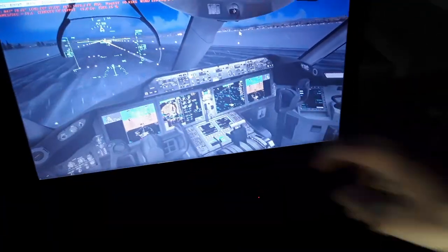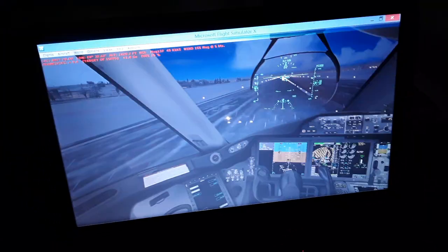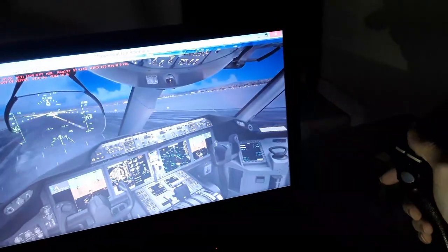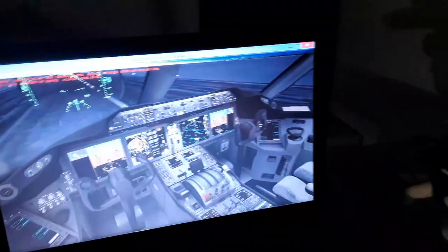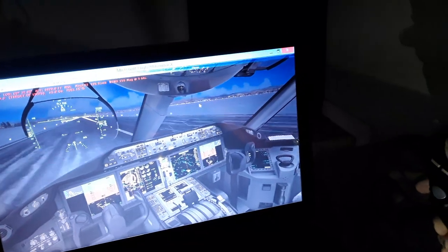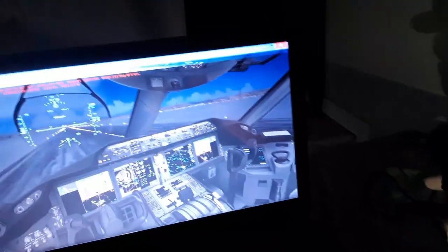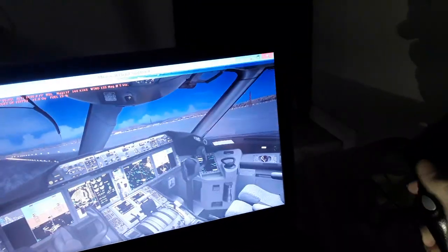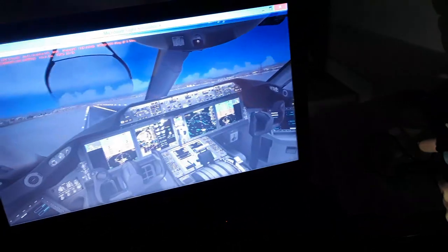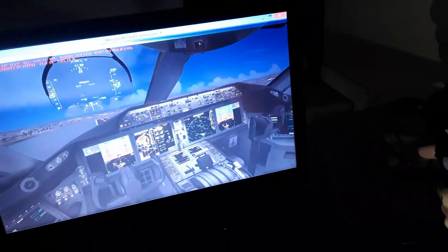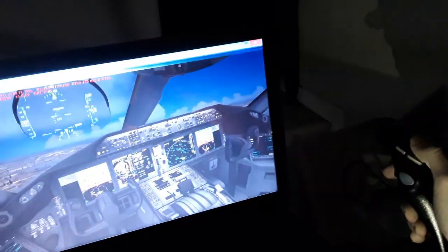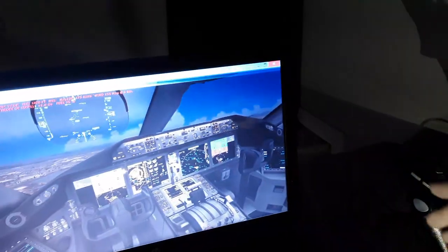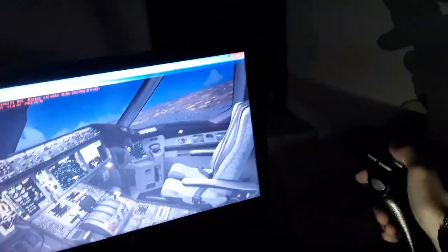So you see takeoff, go around thrust set, push the side stick down a little bit. Also flaps up for takeoff. So we push up. We have 130 V1. We rotate V2. We pitch 9 degrees for takeoff or less to not hit the tail in takeoff. So we pitch up slightly like this, as you can see.